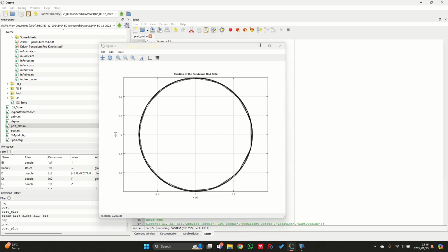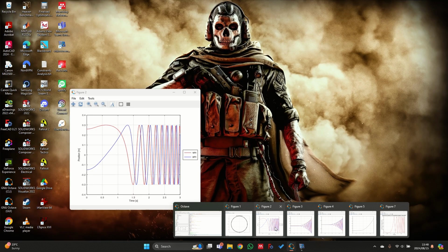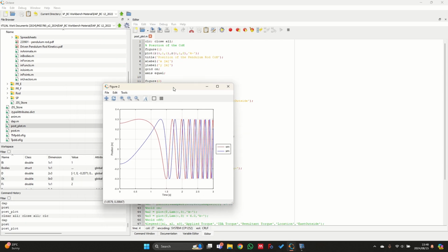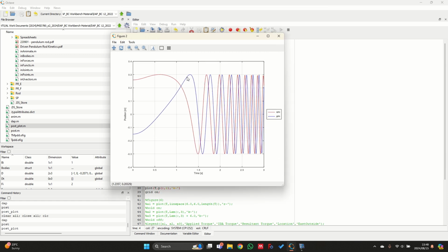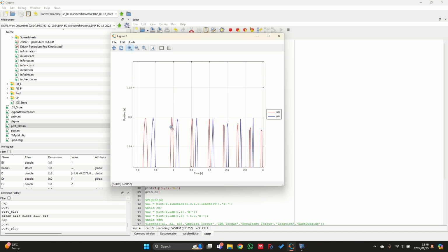Okay, and we can actually see this in the data as well. So if I go to, let's say, the coordinates of the points with respect to time, we see initially, since we still have a ramp up of the velocity, this smooth curvature. So it's fine for the initial motion of this pendulum rod. However, as soon as the acceleration takes over and causes a more rapid response for the pendulum rod's coordinates, we can see, if we zoom in over here, these spikes in the data.